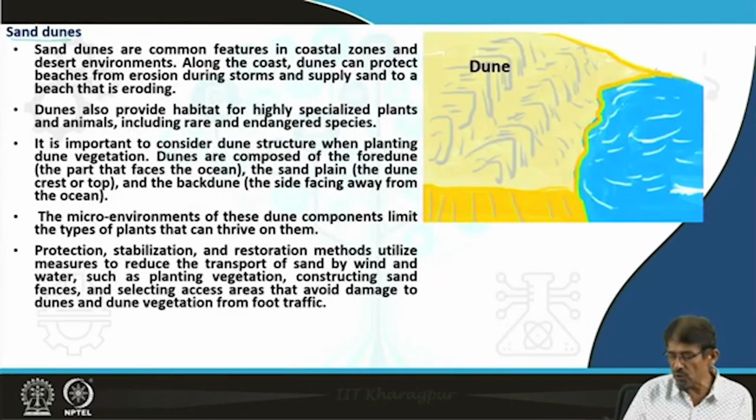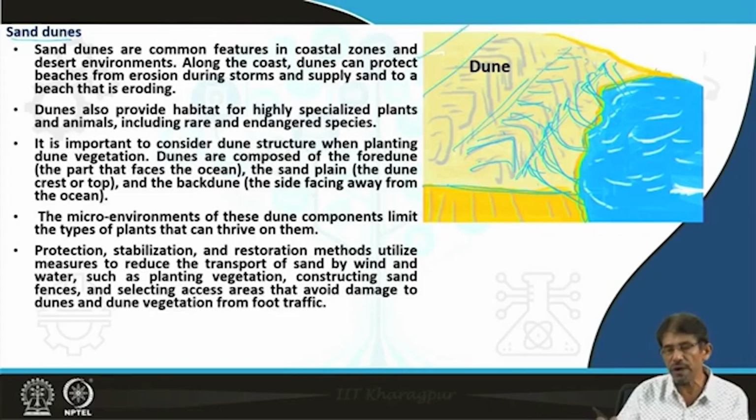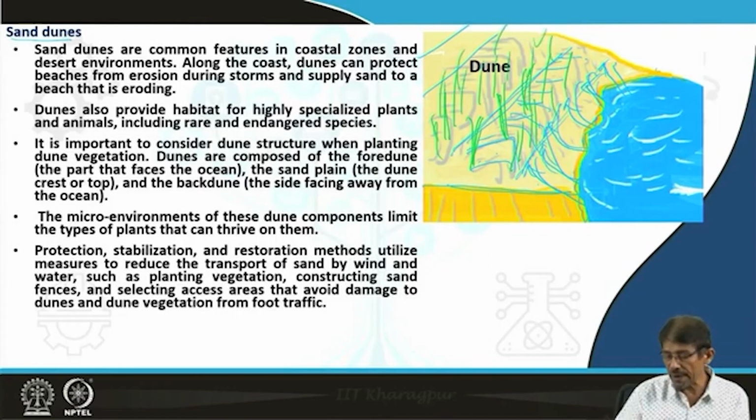Besides this, we have sand dunes. They may be natural, and we are also able to create this type of structure. Sand dunes minimize the impact and absorb the energy of waves, divert the waves, and partially absorb and break the energy of waves when they are normal to the movement of sea waves. Such structures located naturally in the coastal zone support the stability of the coastal zone. Nowadays we plant a number of grasses and trees to provide stability to such dunes. Such a soft technique is preferred to reduce this type of impact.